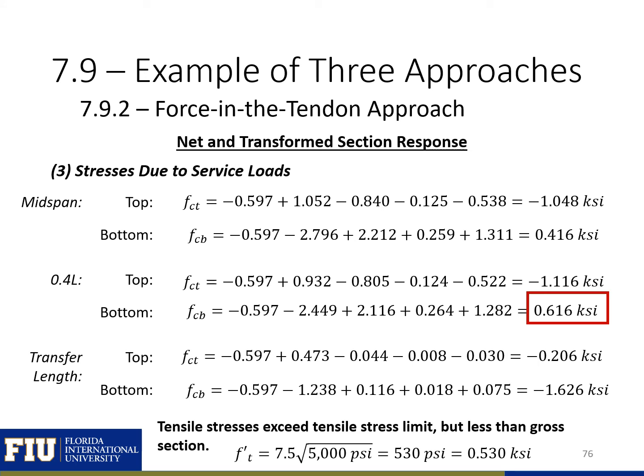Shown on this slide are all of our calculated stresses due to our service loads at our 3 locations. So you can see we still are exceeding our stresses at our 40% length, but the calculated stress is less than the stresses that we had with our gross section.